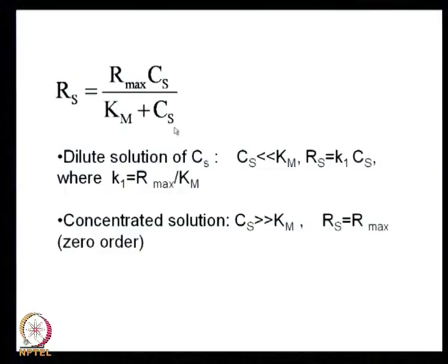That is what we are trying to do, and most of the problems that we are going to solve here, we are going to solve first using first order kinetics, and then using zeroth order kinetics, and we understand that our real kinetics and real solution lies between these two. So our actual solution will be bounded by the two solutions that we get. That is the strategy that we will follow. Now if you want to do this on your own with the real kinetics, you simply have to solve this numerically.